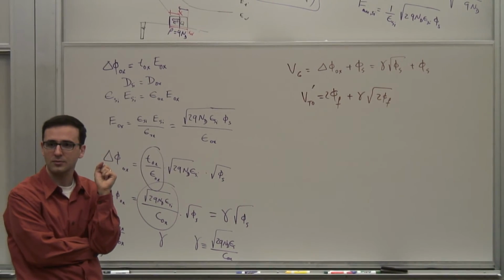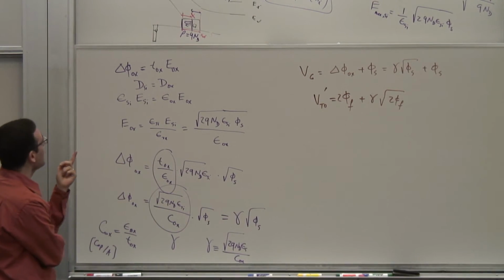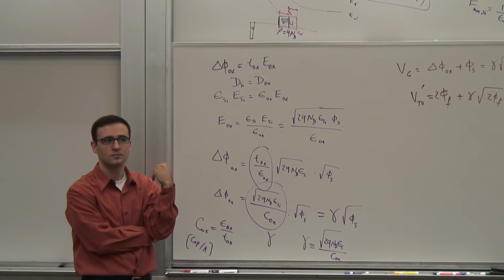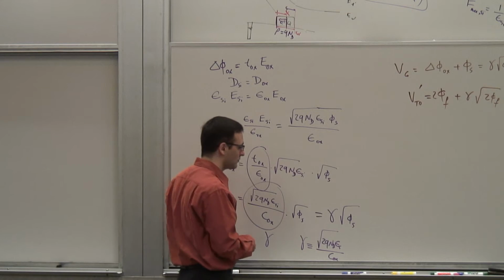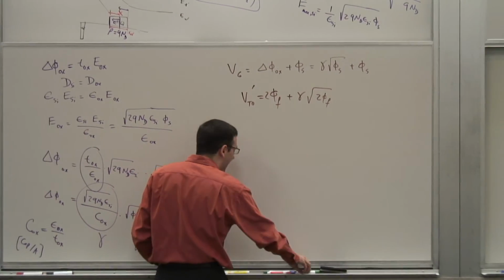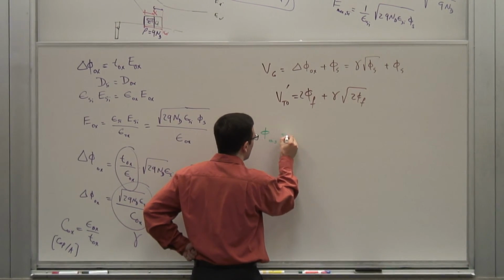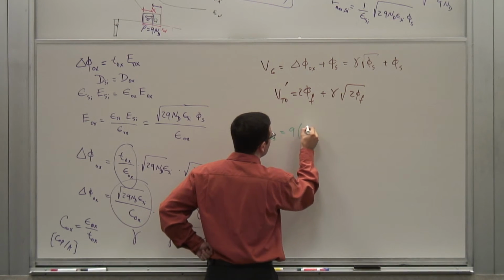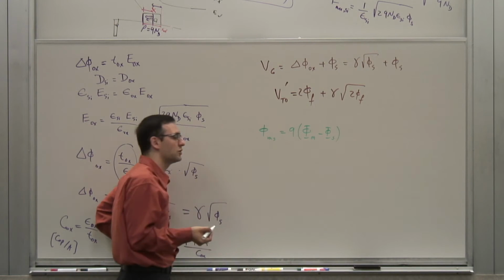Now let's go back to those assumptions and see how we can deal with them. Actually, it turns out it's very easy to deal with them. Now, one of the assumptions was that the work function of the metal and semiconductor are the same. Right? Which is not necessarily true. So now if they are not the same, what happens? If they are not the same, you can calculate the difference between them in terms of voltage. So it's basically q times Vm minus Vs.